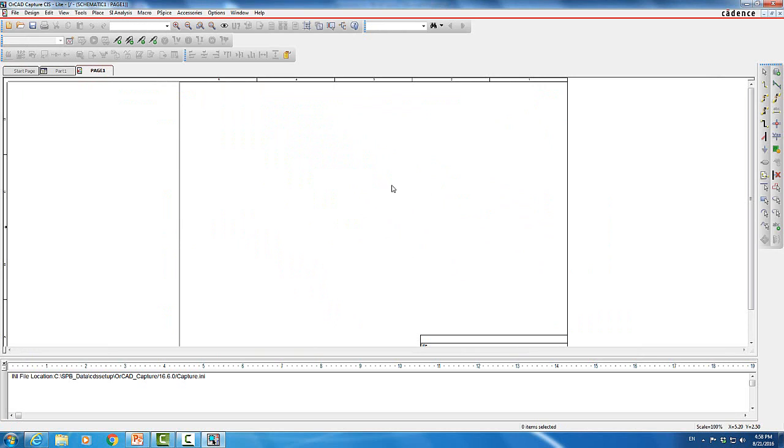Now you have too many options to go through, but we will not go through those in this tutorial. We're basically going to show you the basic things that you need to do to run those 3 simulations. So the first circuit we're gonna run is a voltage divider, and we're gonna apply a DC voltage source, but we will vary the value of this DC voltage source. So this is called DC analysis or DC sweep. I will basically vary the DC voltage from some initial value to some final value with some incremental steps. So it's a very simple circuit.